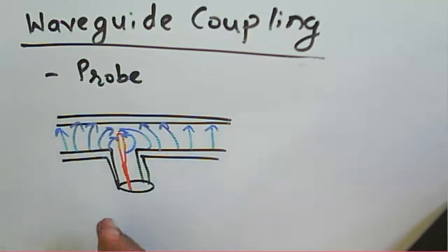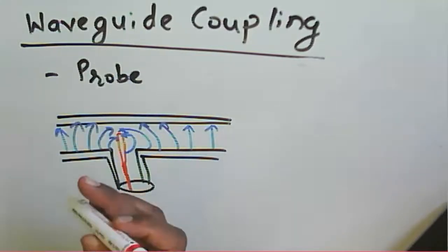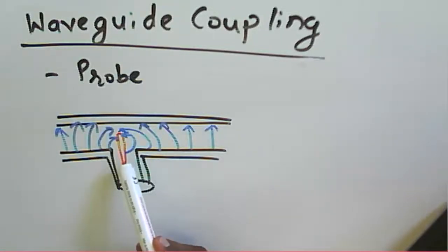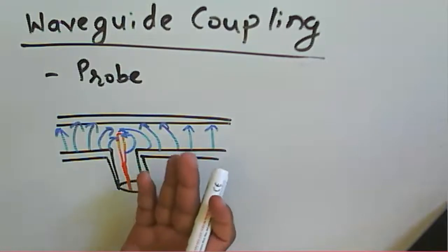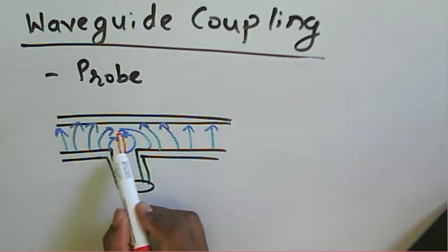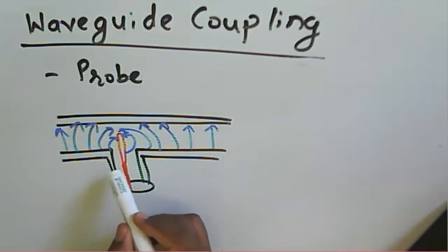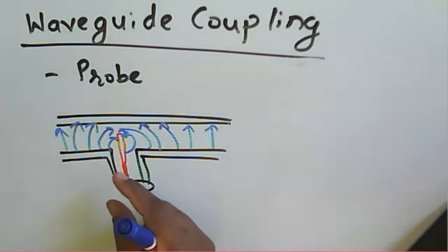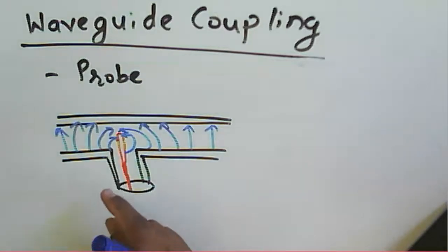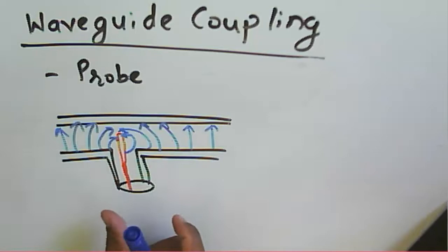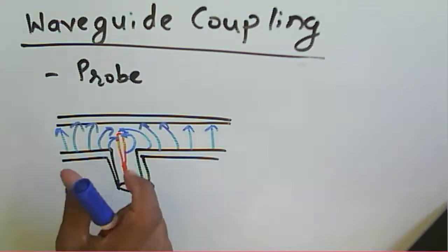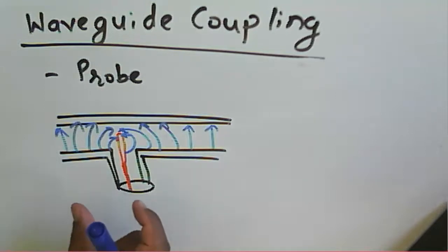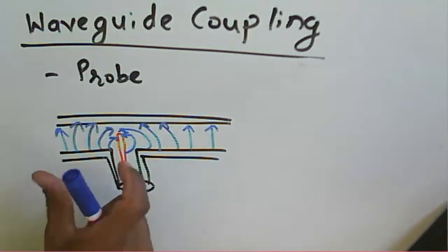when we need to take out the power from the given guide, then based on the length of this particular probe, the energy taken out through this probe will increase or decrease. So what we can say here is that the size or shape of that particular probe will determine the power handling capability of your guide. Again, it also depends on the place where we put that probe.